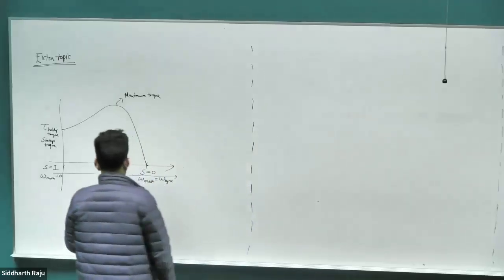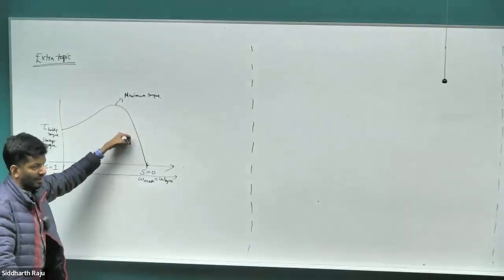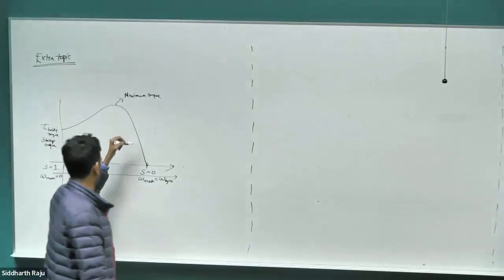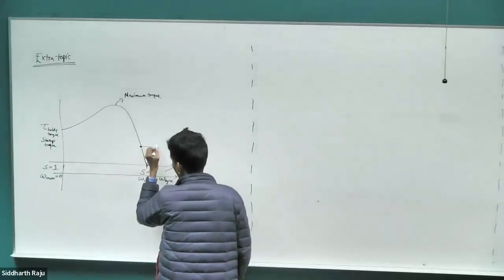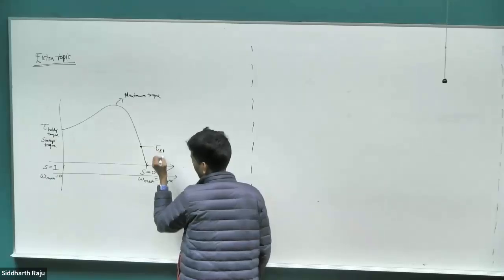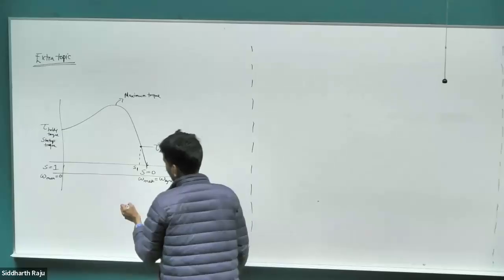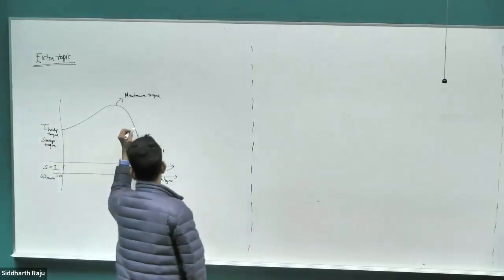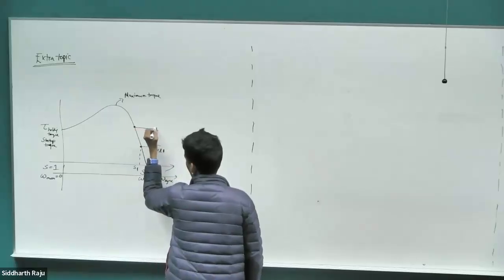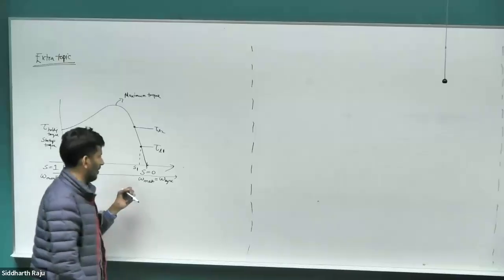When we are in this region, the motor is going to operate in a stable manner. If we say we are initially at this point, our load torque is, let's say, tau load is here, then the corresponding slip at steady state will be some S1. Now, if we were to increase our load torque, let's say our load torque doubles, and we go to this new point, tau L2. Now, what's going to happen?